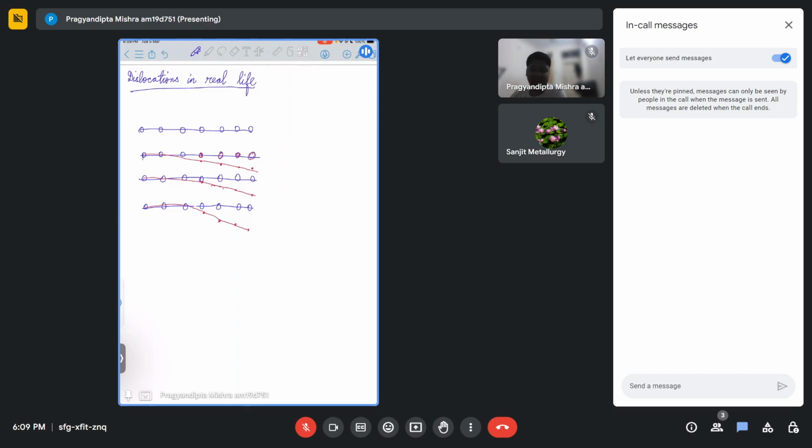Essentially, you will have a dislocation line, which goes from this atom here, where the bending is starting, and it will go something like this. This is your dislocation line, the one I have shaded. Now at different points in the dislocation line, we can see a relationship between the dislocation line and the slip vector or the Burgers vector, right?